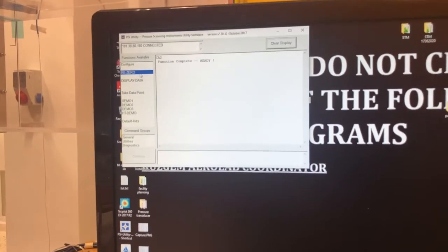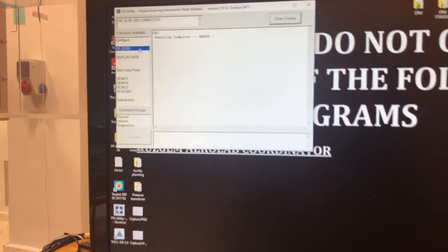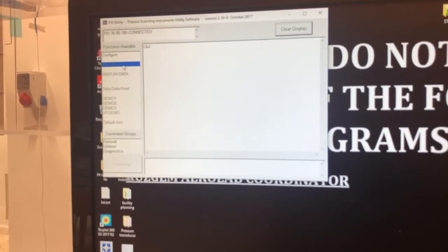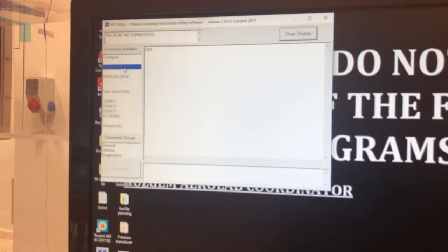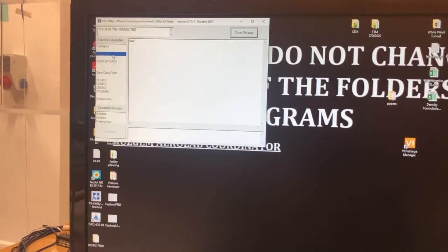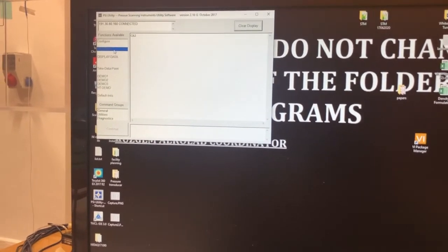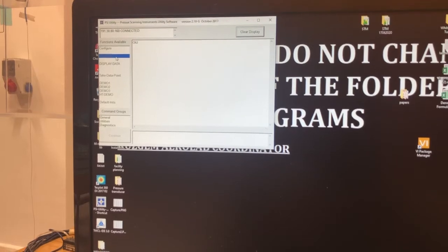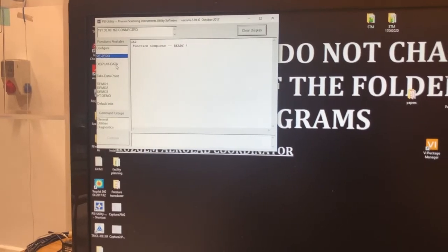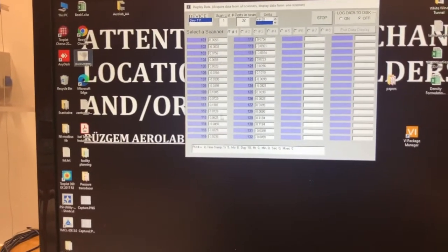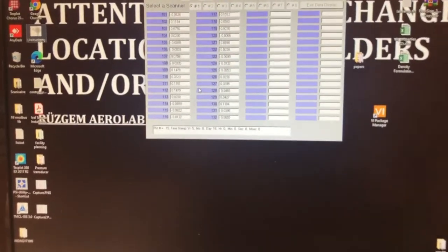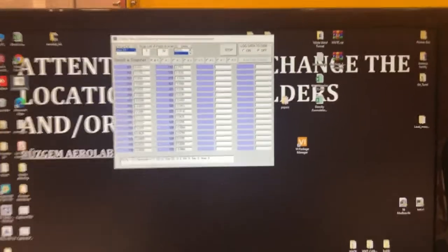Before collecting data, we re-zero the data acquisition system. Let's do it together. We press this, and then we hear a clicking sound. We wait for a few seconds. There's a clicking sound again. And now calibration is done. It means all the pressure values in all the channels oscillate around zero as the tunnel velocity is zero. This means the data collected should be reliable.